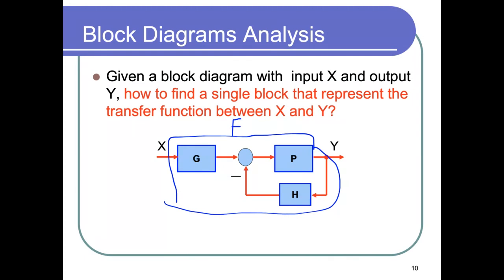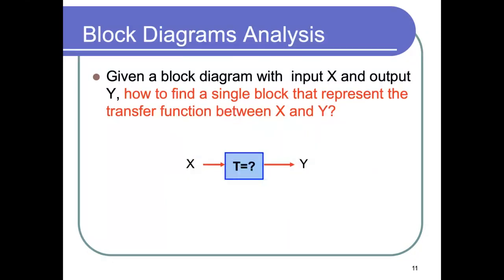and then I can know that Y is equal to FX, and if X is a step input, then it's just F over S, and with that, I can see how the system will behave for a given step input easily. But if I don't have block diagram reduction, then things can get complicated and you might need to deal with multiple equations and multiple unknowns. So that's the purpose of this unit. We'll have some basic rules for block diagram reduction and apply these rules to study the input-output relationship of the system.